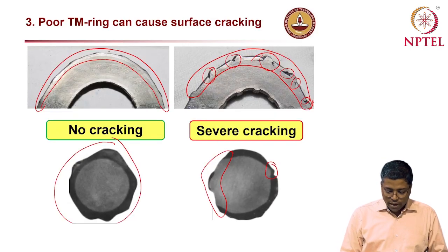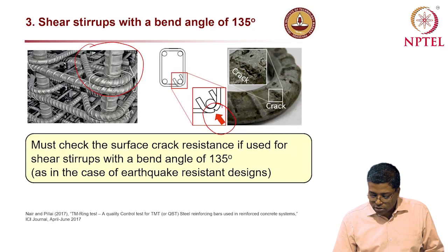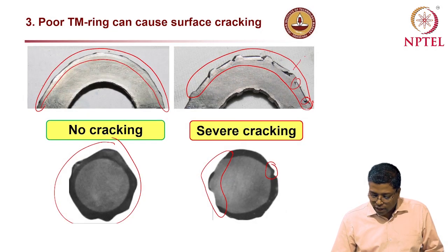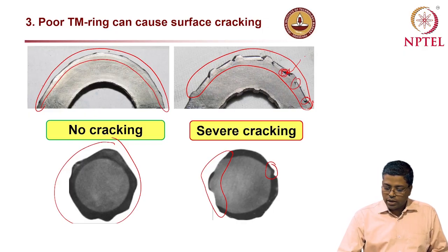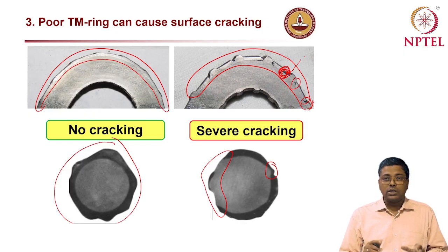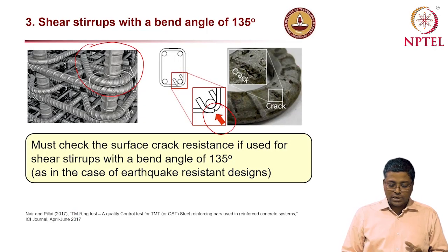So if I go back to the previous slide here, what will happen is, if I have a crack like this, chlorides can enter through this, go into this crack and then stay there, and then it will start corroding deeper and deeper right here. So some kind of crevice corrosion can happen. So that is the danger.